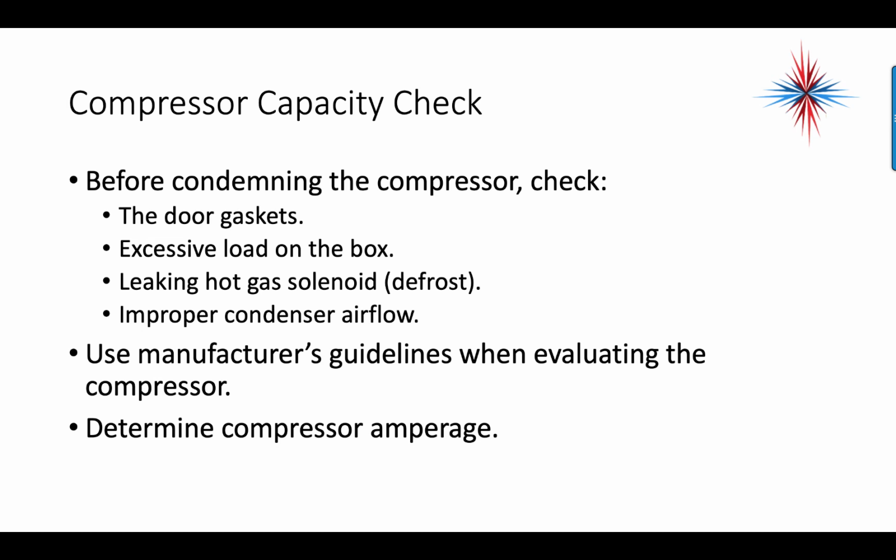Domestic refrigerators are just a lot of parts in a small space. So you'll get to a point with them where it's not easy enough to repair, like anything that's in the cabinet itself, between the walls of the cabinet. To repair that, it's usually better just to replace the refrigerator. So always when you're dealing with a customer with domestic refrigeration issues, take a look at the cost of repair versus replace and give the customer both options.